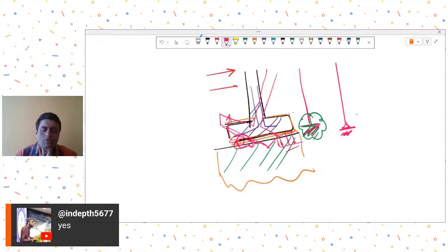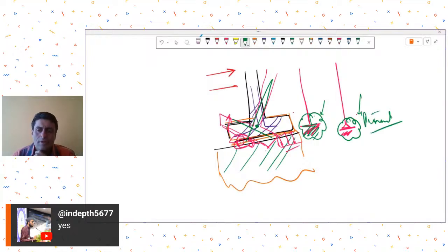So at that point this system undergoes a rotation. If it undergoes rotation, then engineers or book writers think that it can be idealized as a pinned condition. In general situations, it is more like a fixed condition. In this kind of situation, it is more like a pinned condition.